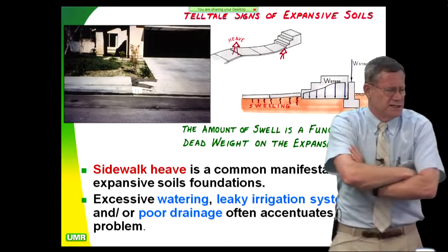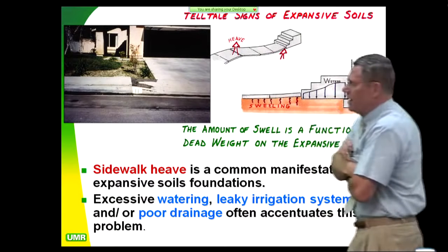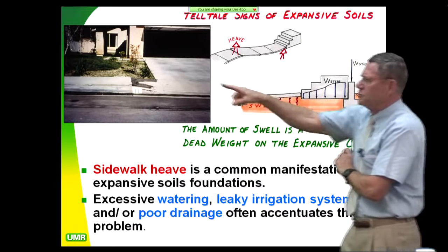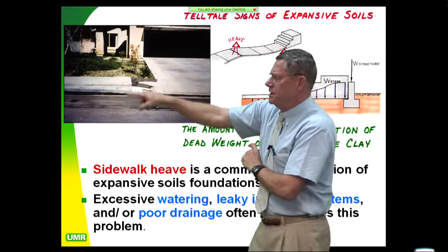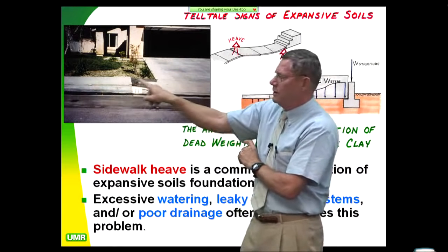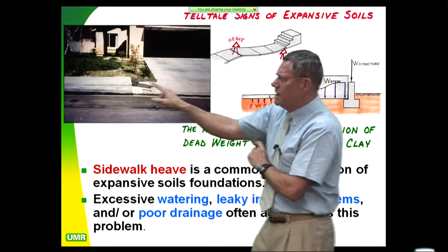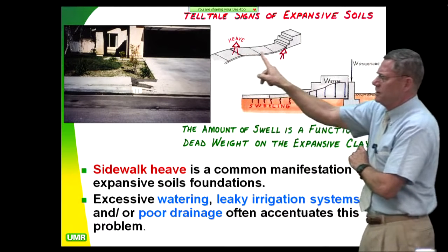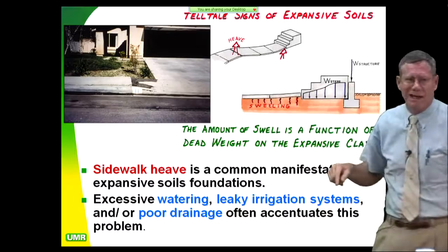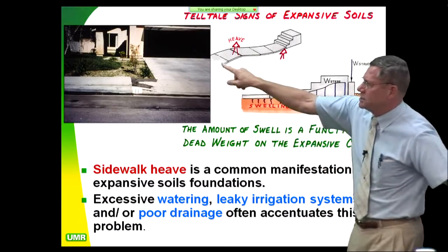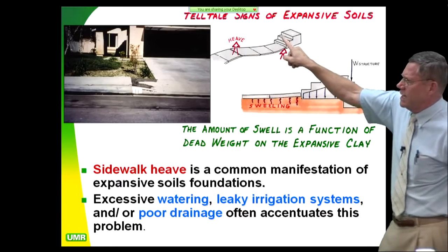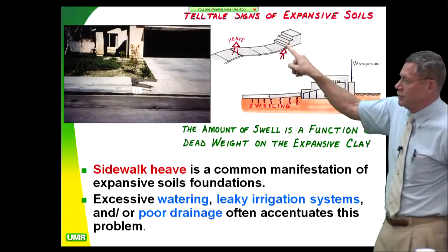What are the telltale signs of expansive soils? Well, you don't have to be a rocket scientist, you just have to have a little bit of training. One thing is you drive by the residence and you look for a heaving sidewalk or a heaving driveway, heaving flatwork. Flatwork doesn't weigh very much. A sidewalk going up to a house might be 3 inches thick if you're lucky on a good day, so this is going to heave very, very easily. Whereas the steps are a lot heavier per unit bearing area.